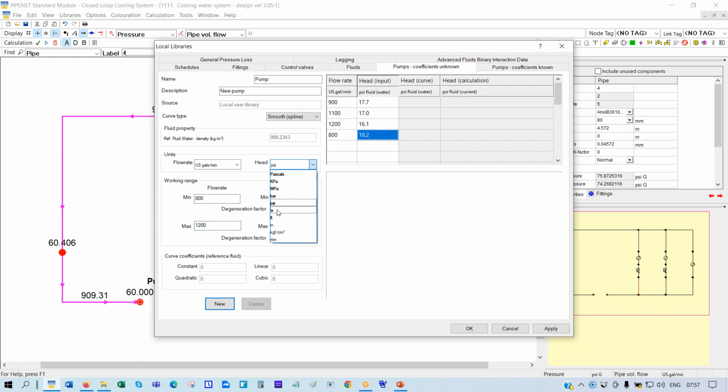See, you can have the pump head in meters because pump vendors normally publish the performance curve in meters head rather than in bar. That's a good reason for that because, as you know, the centrifugal pump curve in meters of head will be the same for all fluids. So that's the reason why they do that. Anyway, here, because this is a demonstration, I'm working with PSI because I won't want to use the same points here.